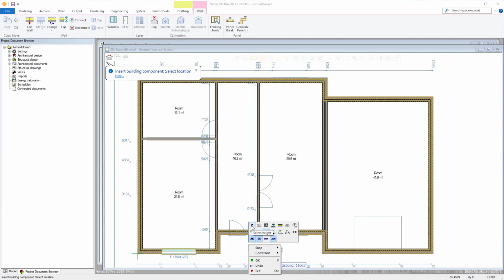The window header height can also be adjusted from what was set up previously in the 3D levels. This will be on a window by window basis, however BD will keep these adjusted settings if adding in multiple copies of the same window. To do this, click the Z button in the contextual toolbar, which will open the Enter Locating Height dialog.